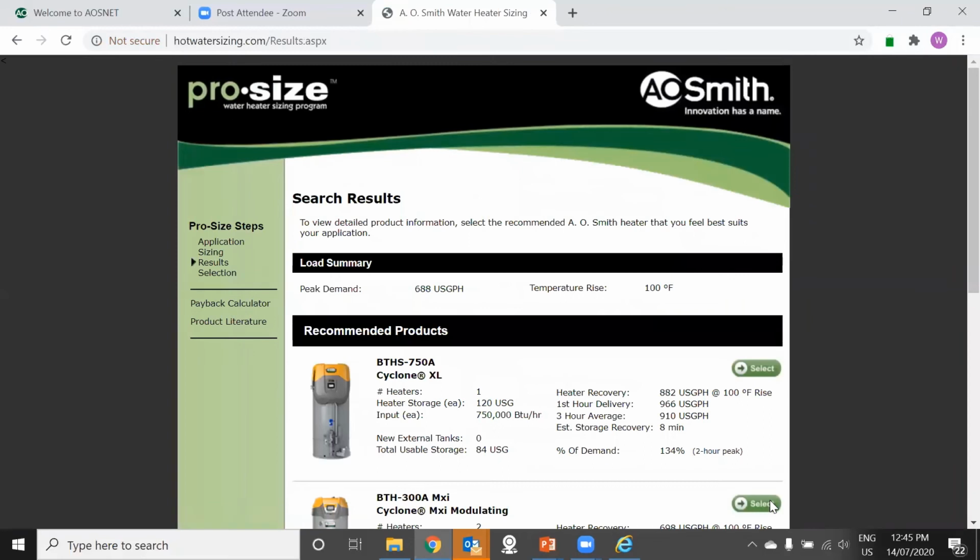And on that point, that extra demand area is great if you have an eye wash in your mop sink area. Depending on the chemicals used for cleaning these days, we sometimes have a requirement for an eye wash in the janitor sink area. So you could add that demand first, do the calculation like Will walked through earlier, and then add in that amount of demand there.